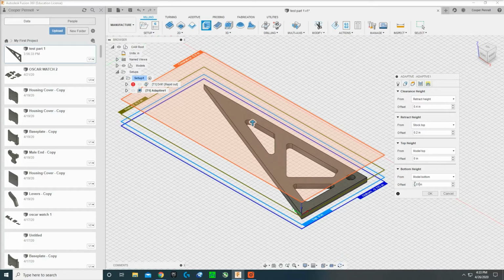And this one is really important because I made this mistake the first time I did it too, where I did not put in this extra 100th of an inch. I think we did it on our first cut, even at Trace's building, not even at my house. We didn't do this, and what happened was we had about a 2 to 3 thousandths of an inch layer of aluminum along all these pockets, and you can't really get rid of that.